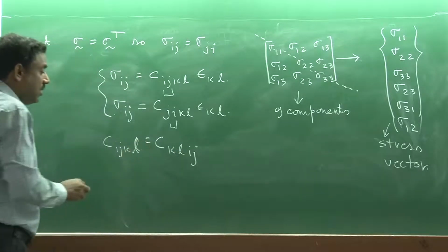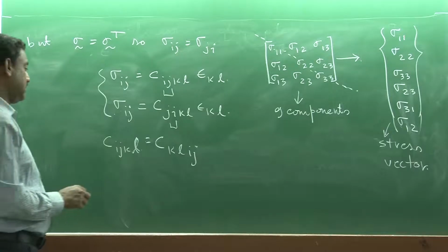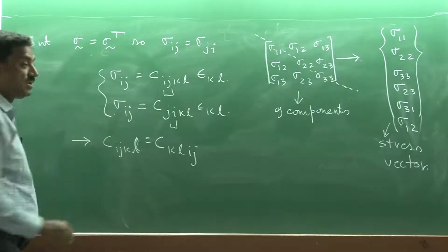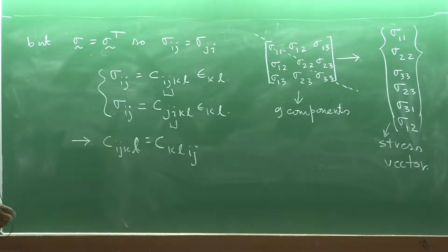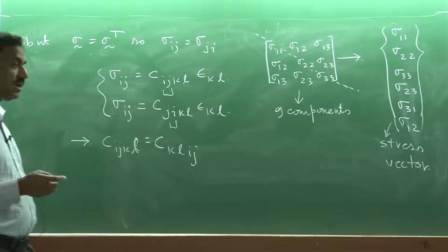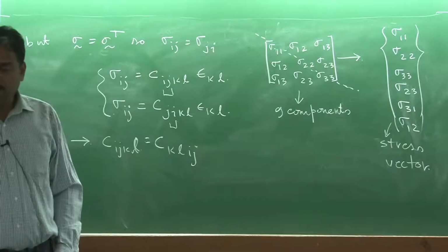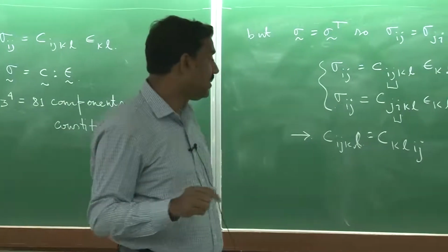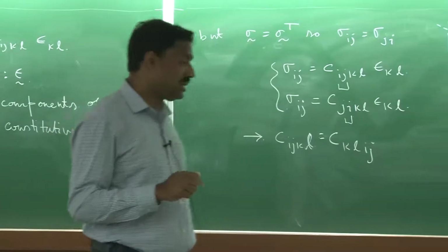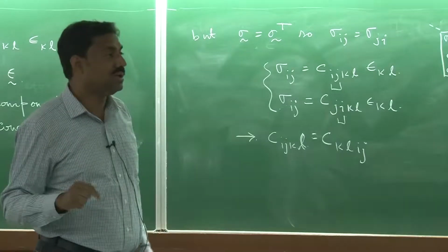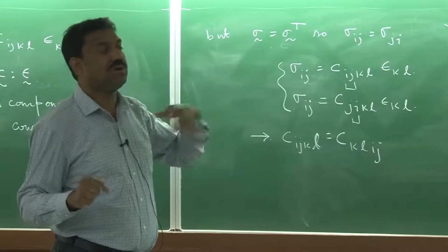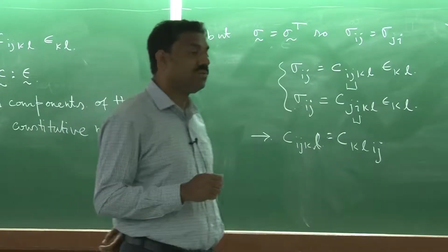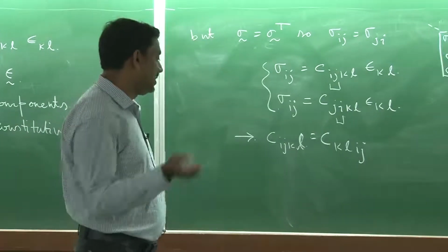This is coming because of the reciprocal theorem. We have all heard about the reciprocal theorem, right, Betti's reciprocal theorem, that if you apply a unit load here, whatever the deformation at another point, if you apply a unit load at that point you get the same. So, there is a positive flow of energy in the path, right, and this is reversible.